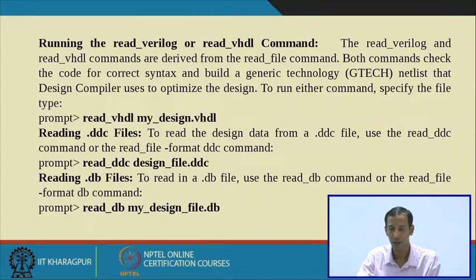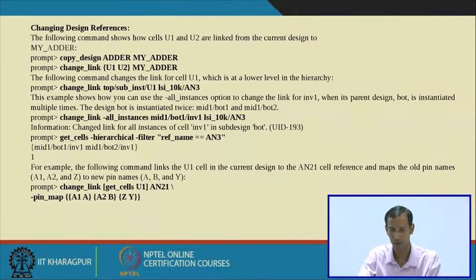I have already discussed how to read. read_vhdl will read a VHDL file, read_ddc will read the database file, read_db will read the .db file, and read_verilog will read the .v file. So this is the command which you can run in the DC environment.